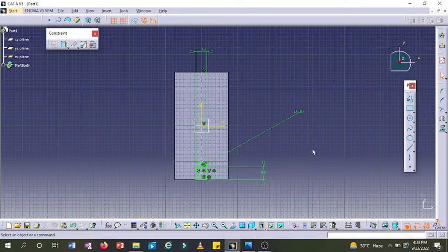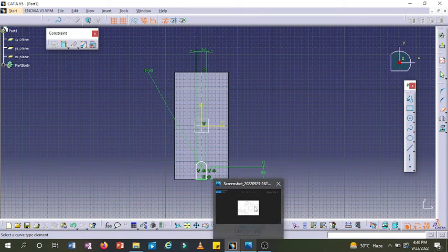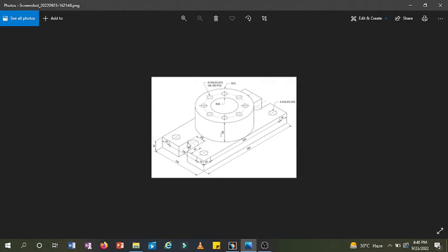Now I trim the parts that are unwanted. Go to trim, quick trim. If you don't want to trim and come back to click trim again and again, you just double click it so that you can trim your stuff without having to come back. We have done it. As you can see, we have drawn the shape that they want, but now we have to make a hole of it downwards up to the last. As you can see, it's up to the last.